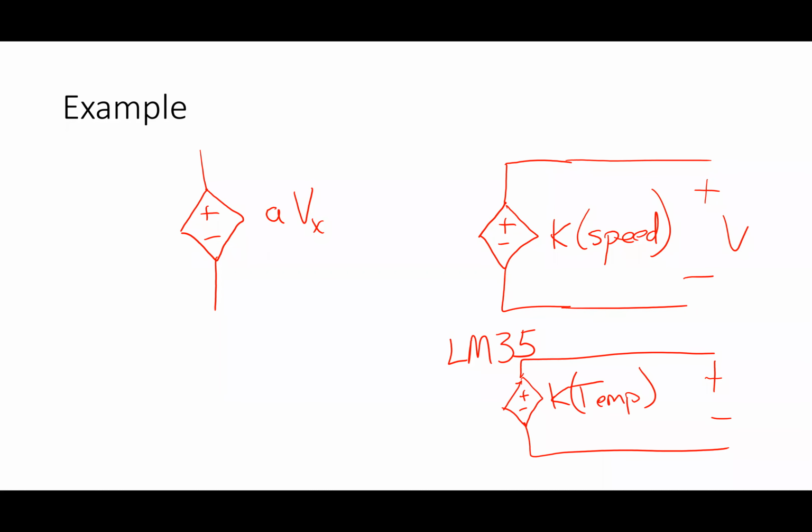So transistors, which you'll learn about in electronics, are voltage dependent current sources. One of the things people ask is, why do we learn all that stuff? You can see a resistor, you can see a voltage source, but it's hard to see a dependent source. There is no such thing as a dependent source, just so that we're clear. The LM35 is a temperature sensor. The mathematical model for that thing, which allows us to design things with it, is a dependent source.